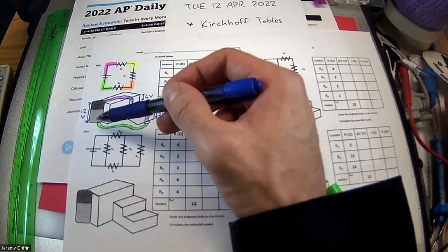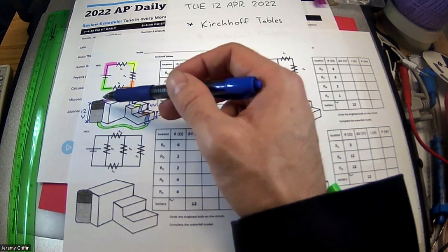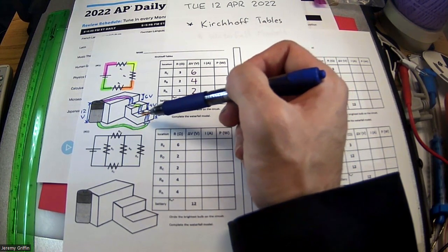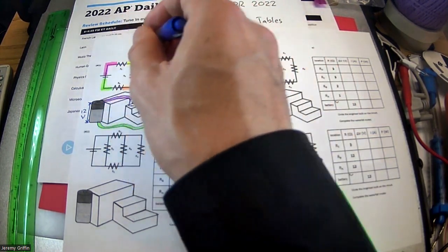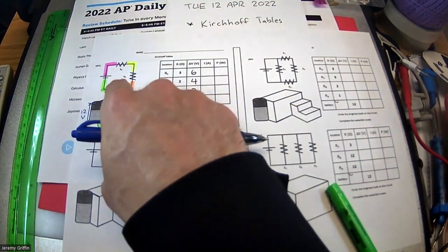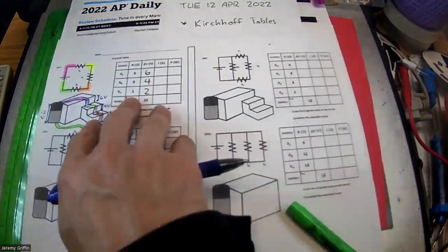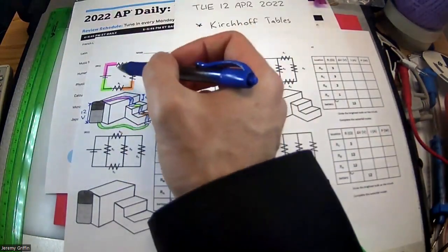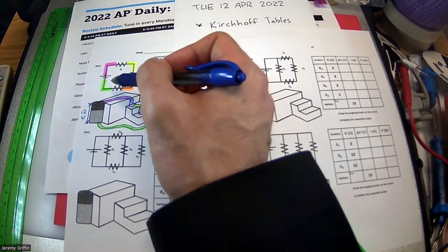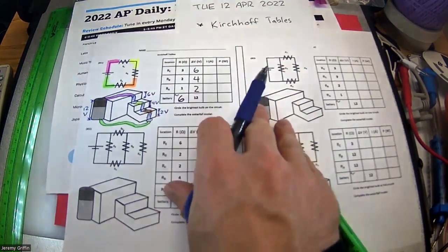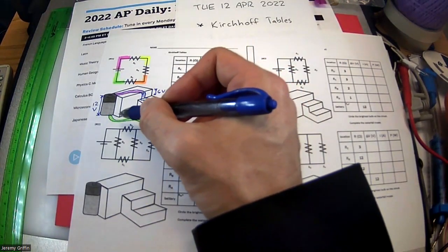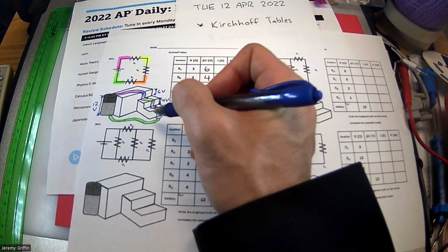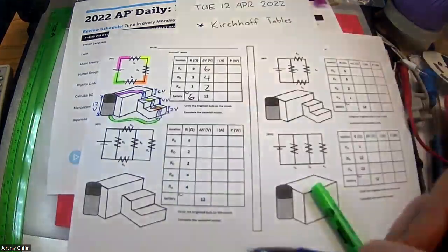Do you guys see that the amount that the pump pumps up the water is exactly equal to the sum of the heights of the waterfalls? That is actually what Kirchhoff's loop rule says. If you can identify any loop within a circuit, and this circuit is just a very simple loop, but this will work even for other circuits, just identify some loop. If you pick a point and go around the loop, the voltages have to sum to 0. In this example, it gets pumped up 12 volts, and then falls down 6, down 4, down 2. That also sums to 0, doesn't it? And then you're back in the valley where you started. Okay, that's that.